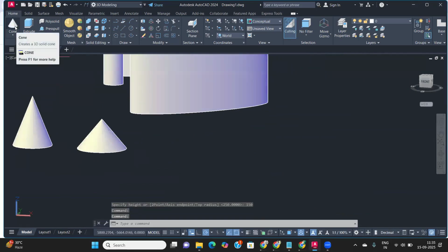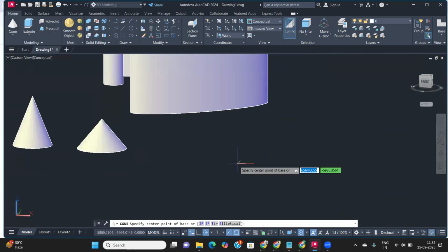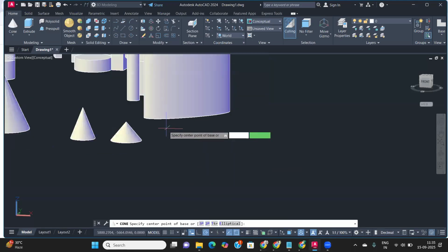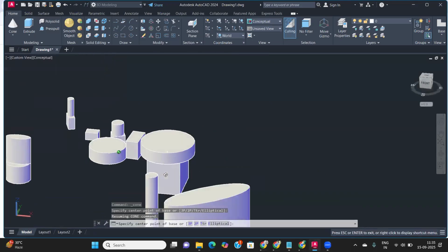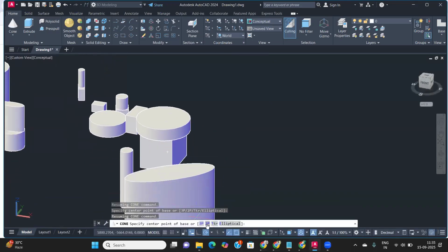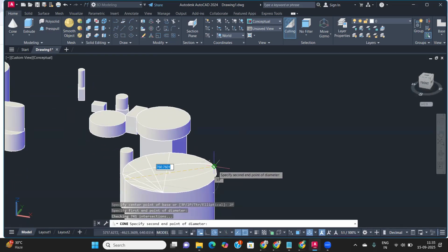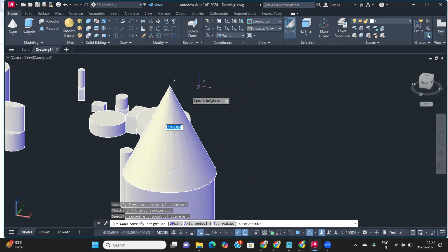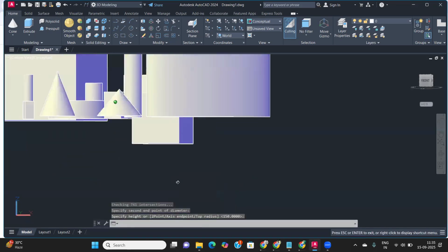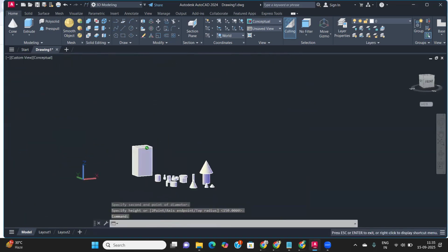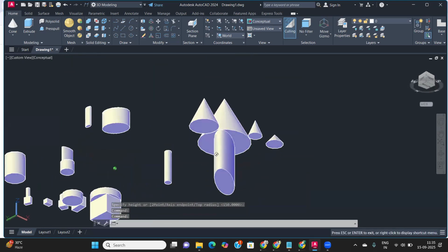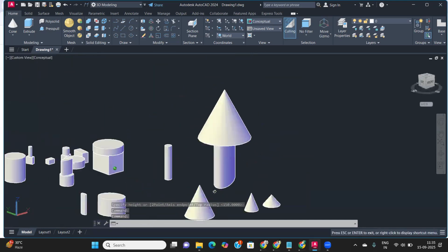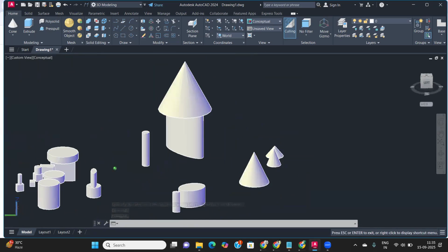The next one is we can use the circle by 2 points or 3 points, whatever you want. Suppose I want to show here by use of 2 points, just click on 2 points first, and then select the first and second points, after that you create this portion, okay? And on behalf of this part you can create. This is your simple 3D object created this way, right?